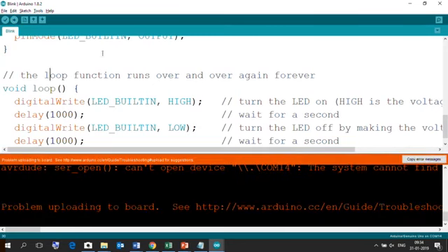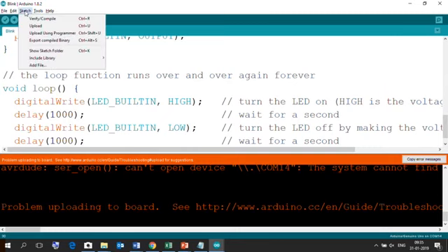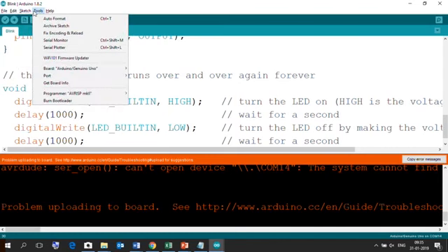Alright, here is one error that we see. The point that we had discussed before uploading the sketch, your typical Arduino program that you are writing is a sketch. You have to go to the tools option here. Make sure that both the menus, board and port, are properly enabled.